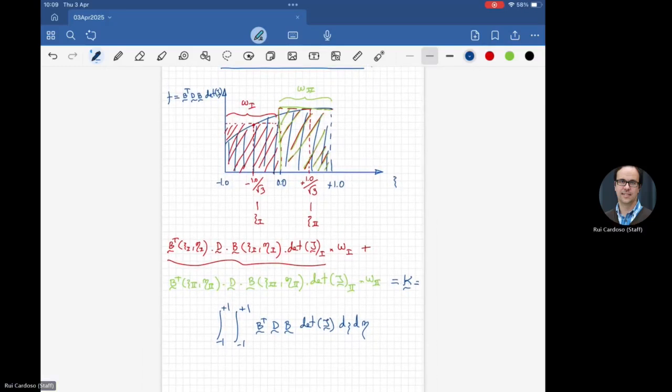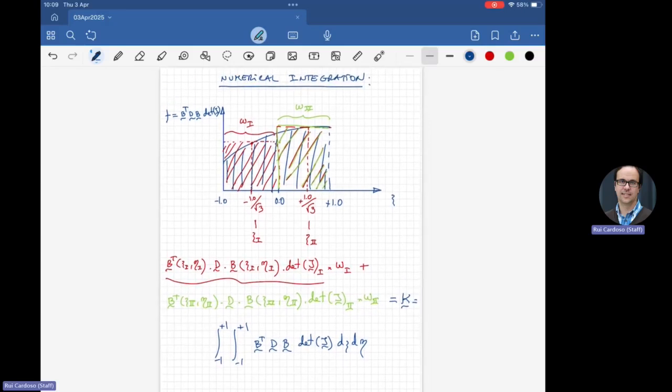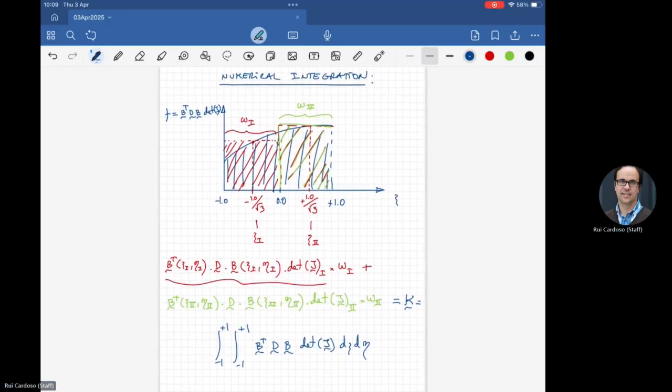Okay. So I think this slide, as it is, shows you well, in my opinion, of course, the numerical integration scheme. So look, we are aiming for the area below the curve in blue to be our analytical integral that will deliver our stiffness. We're going to replace this analytical integral with numerical integration, which in this case considers 2 points in the x direction.